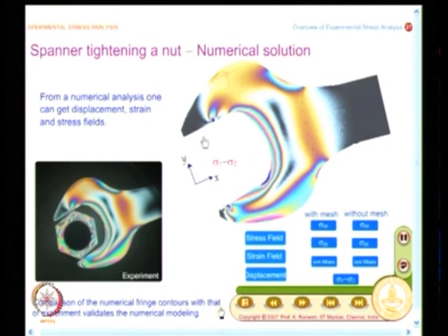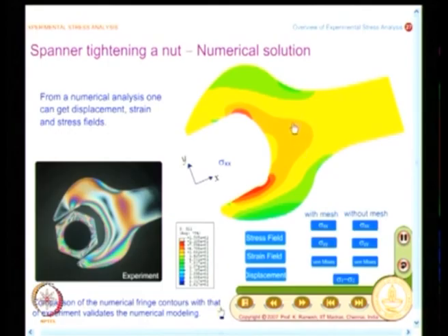And if you look very closely, I have this as a stress concentration region, and what you see on the screen, my students have taken a little time to apply the boundary condition appropriately until the experimental fringe pattern matches closely with the numerically simulated results. So, both the choice of elements, discretization, and also the boundary conditions are improved until you get a close match between experiment and numerical solution. So, you have this. What is the difference here? Here, when I have to find out, I can get sigma xx, but I can do this only by interpolation and based on finite element formulation.